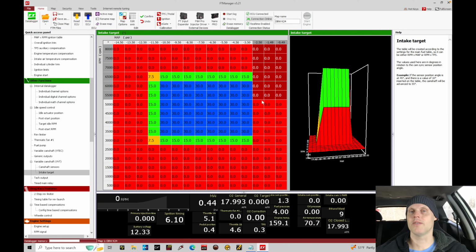How do you determine if your variable cam control change is correct or not? We'll determine that as we unpack all of the data logs and go through the tuning process. We're actually going to be looking at the log data and making some educated guesses as to what is going on with the power band. And then we'll take a look at the Mainline screen and actually look at the dyno pull to see if what we're finding from the log is matching what we're seeing actually measured with the engine's power output. And finally, we'll build that cam composite blend.